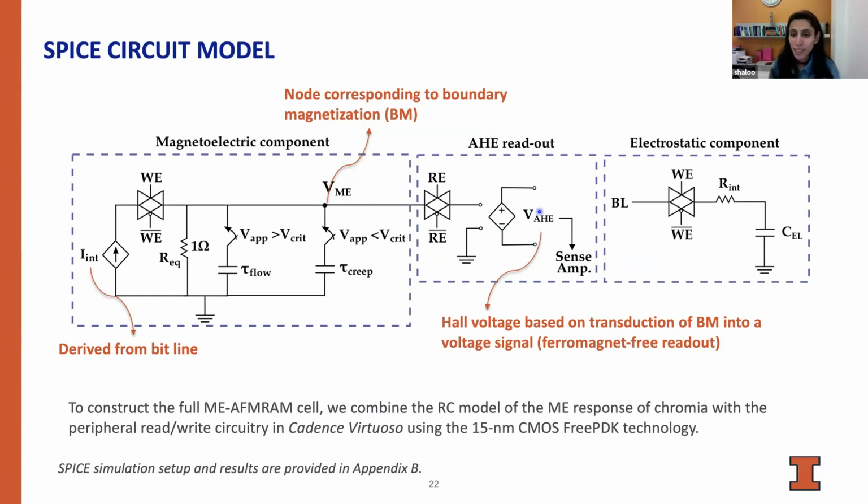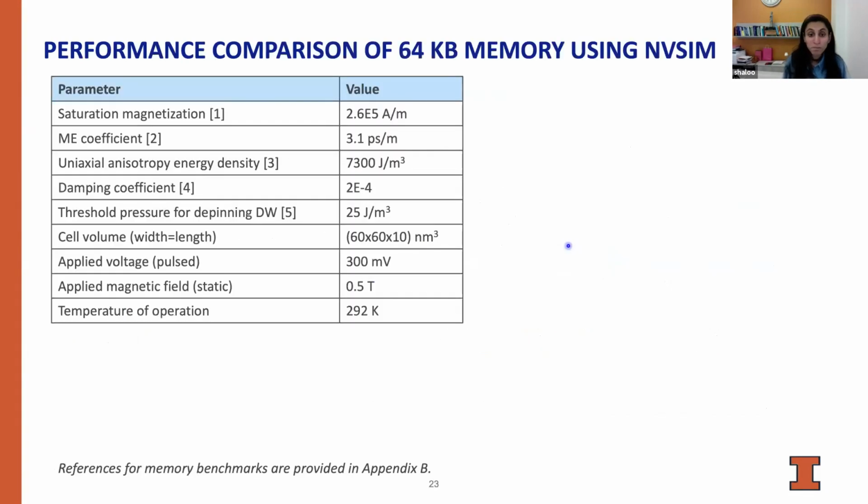They're very small, and in the previous one I showed you 15 millivolts of Hall signal. So what that means is that from a CMOS design perspective, my sense amplifier design gets a little complicated. So that is something that we have to remember when we are designing these memory cells, that getting better transduction efficiency is very critical in order to enable CMOS integration and so on.